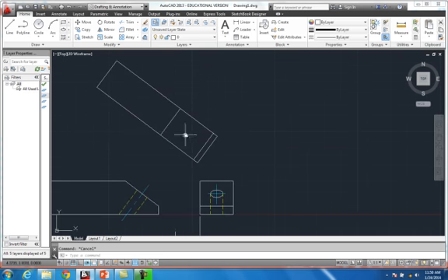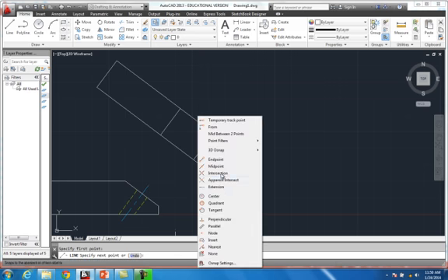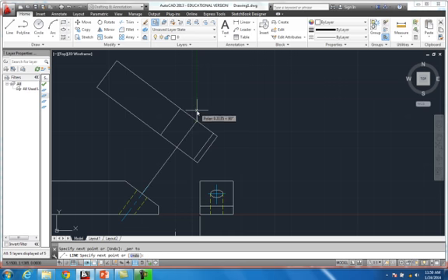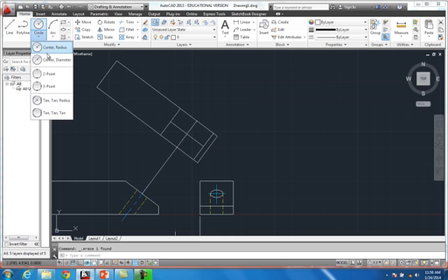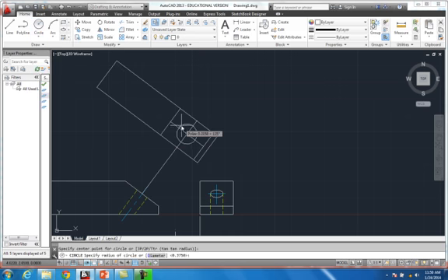Now we just got to put the hole in this, which again come from this point, come straight up, hit your perpendicular to that line, catch the midpoint, and of course midpoint. There's the center point of our circle, and we'll put this circle in. It is 3/8, 0.375, or I could have projected it up. Oh, must have been on diameter. Center radius, and the radius was 0.1875. Enter. And if you were to project from this point up to there, that would be dead on the money.